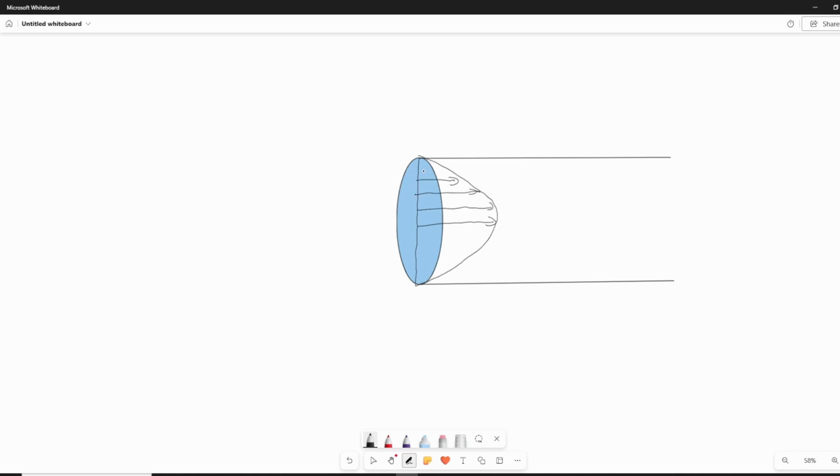So if this is the case, can we set this up in ANSYS Fluent? The answer is yes. Let's just write this down: parabolic profile, inlet velocity. It means that the velocity in the x direction changes with the y direction.